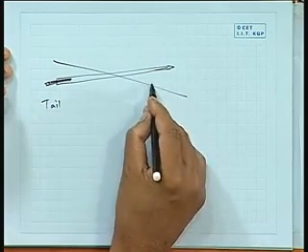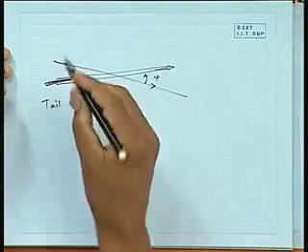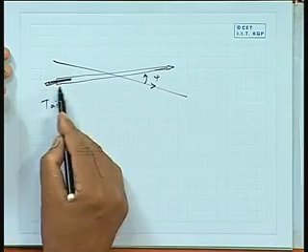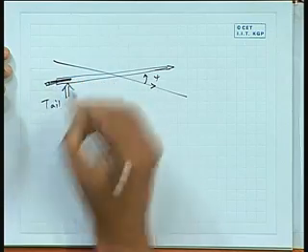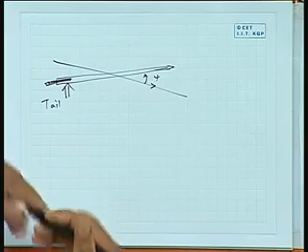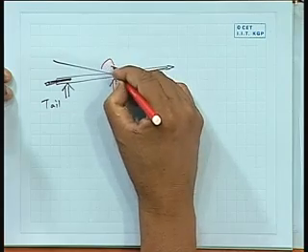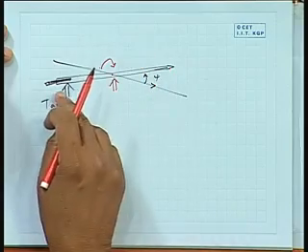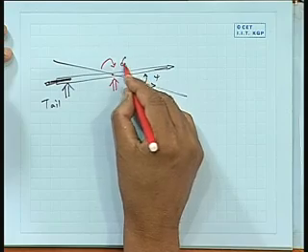What happens? It is supposed to go this side, but now it has turned by some means by an angle psi. Then that would obviously cause, even if it is going on a straight line, the flow going past it, but now the flow is going past at an angle, and I am just considering this part of it, it is going to give some kind of force in this direction. This force is equal to a force plus a moment. Any force can be translated back to another point, or rather this force will give a moment about this center point, let us say the Cg point.